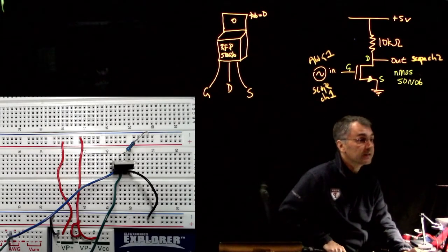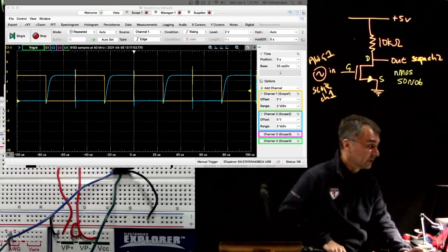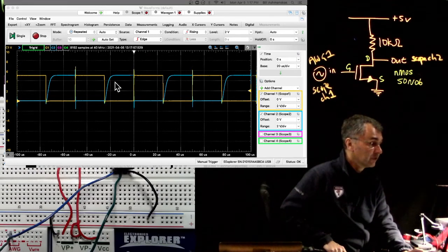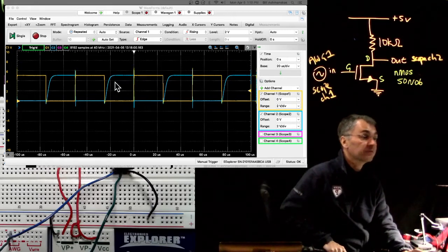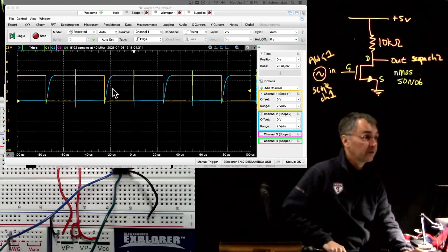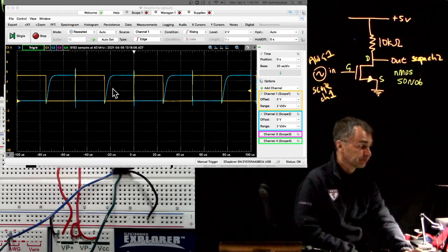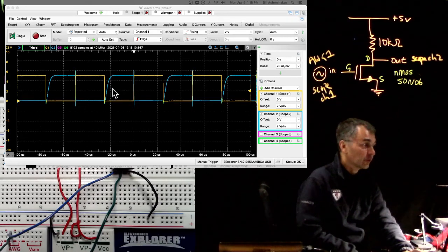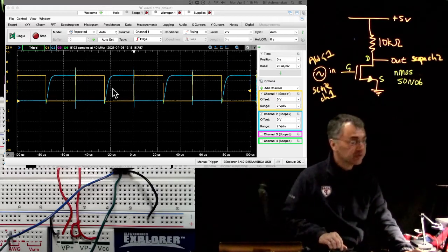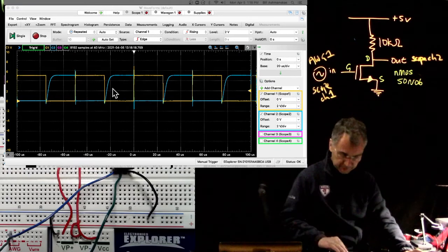And let's look at the display again. Yeah, so look at that. You see, so now it's doing just fine. So you can see that does seem to be that RC time constant, because we reduced R by a factor of 10, and that RC time constant seems to be like an order of magnitude shorter. So I think that's it for 3.1. Then let's move on to 3.2.